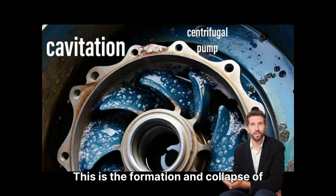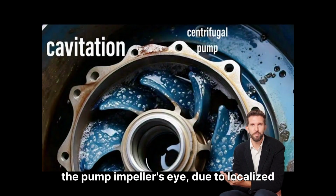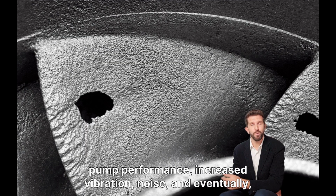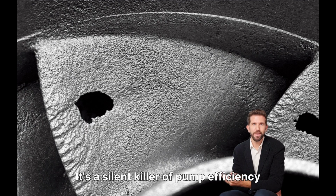This is the formation and collapse of vapor bubbles within the liquid, typically at the pump impeller's eye, due to localized pressure drops. The consequences of cavitation are severe: reduced pump performance, increased vibration, noise, and eventually, significant damage to the impeller and casing. It's a silent killer of pump efficiency and longevity.